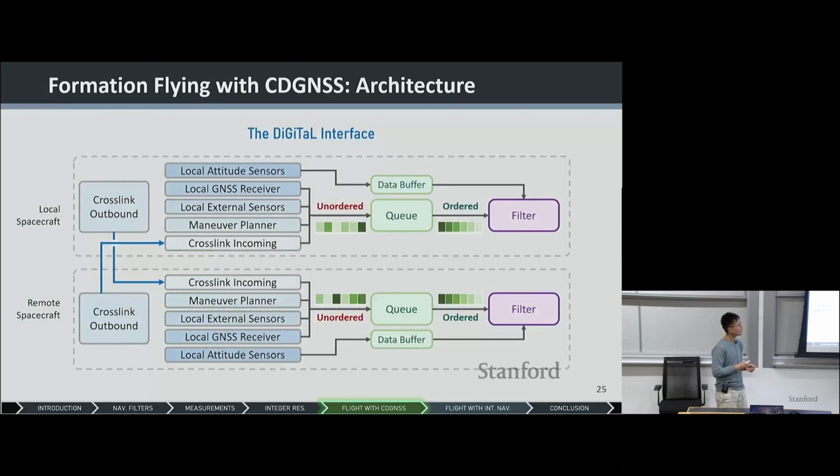So the actualization of interfacing is actually quite precarious because you're dealing with a lot of hardware sources that are running on their own threads, with their own onboard clocks and things like that. So the data interface has a key responsibility. It receives a bunch of necessary information to perform differential GNSS. They'll come in order within their own subsystems, but they may be running on different timescales, and we're not guaranteed that they will arrive overall in time order.